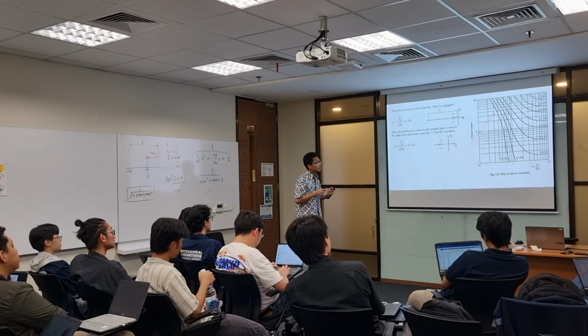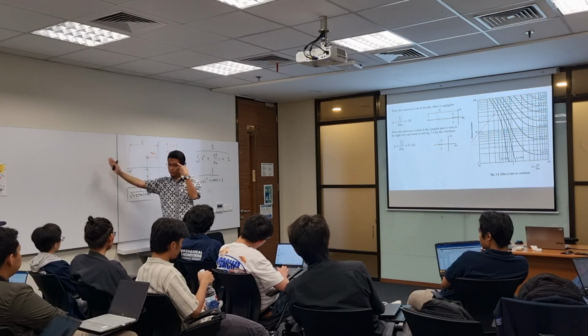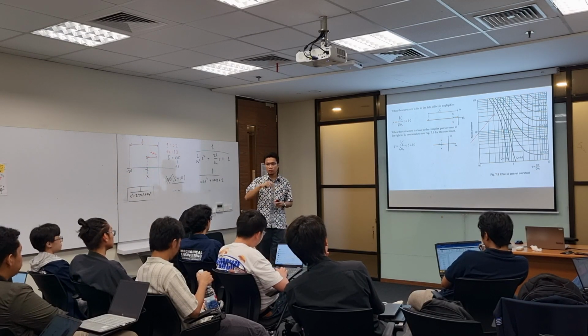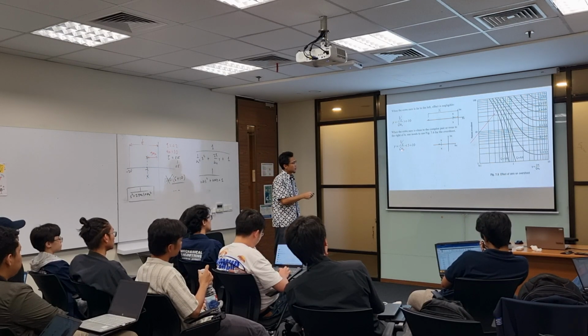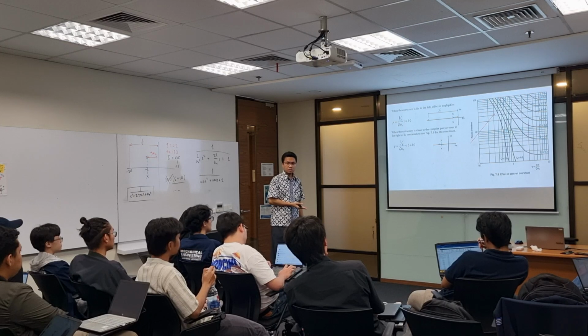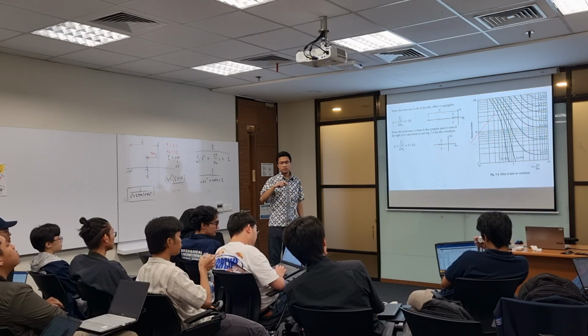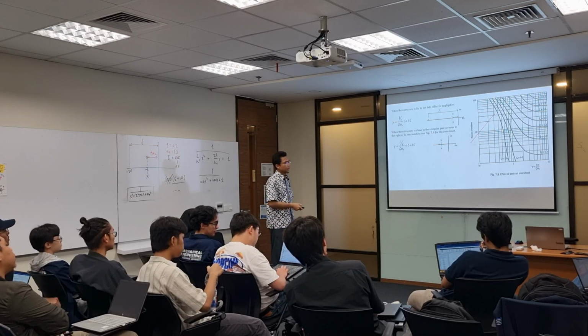If the zero is far away from the dominant poles, far away to the left, then it will not affect the overshoot. It is the same kind of computation that you do, then you use the figure to estimate what the overshoot is. Any question on this?